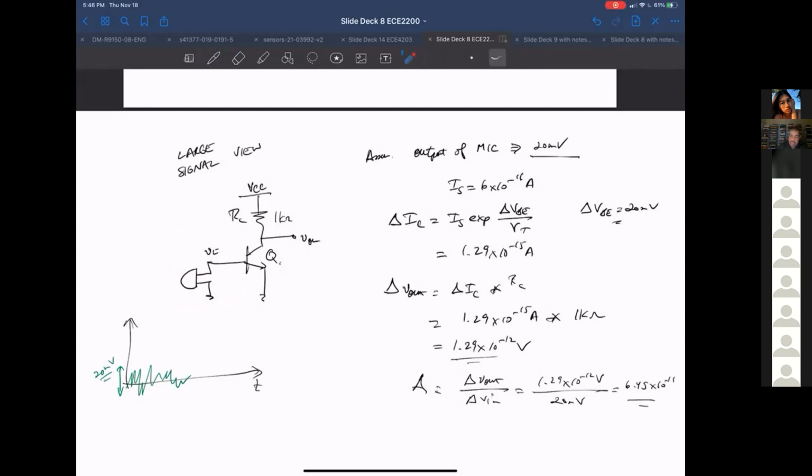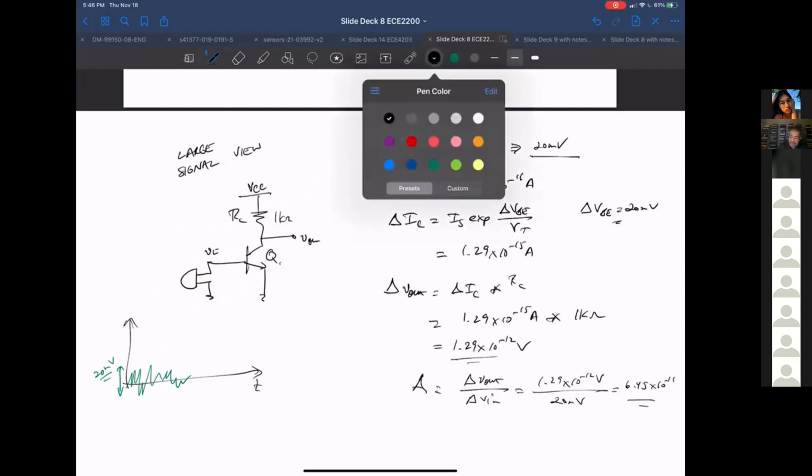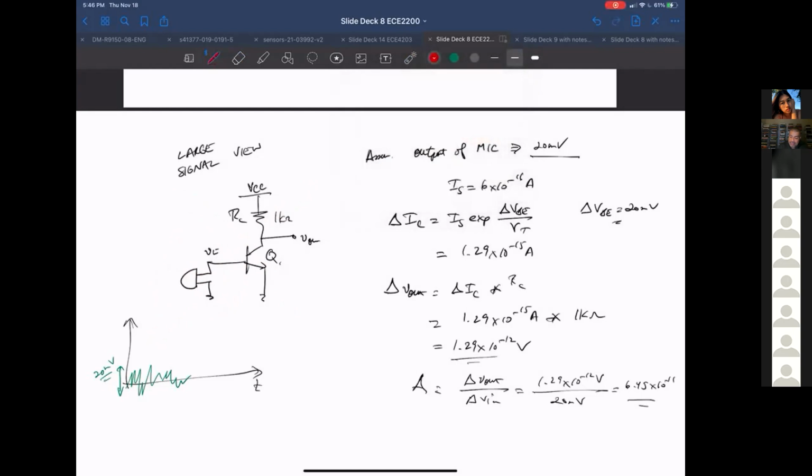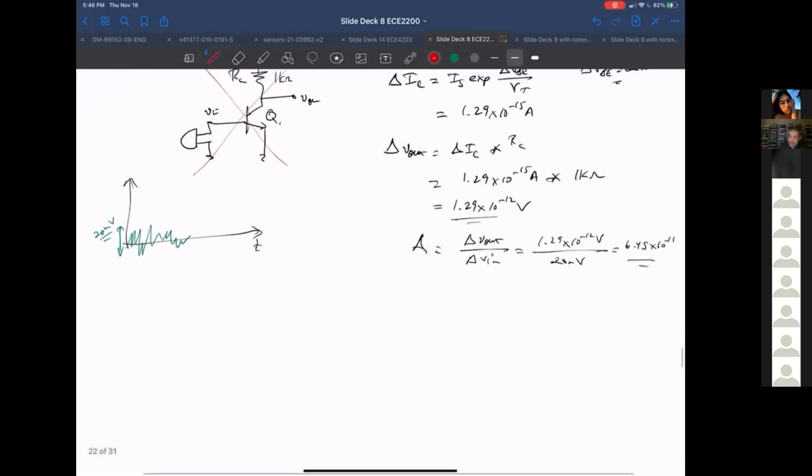Okay, so this thing is, I'm going to guess at least some of you, even after this class, are going to do something like this at some point. I've done it, just not thinking it through, right? Just hook it up straight. You're not going to get anything coming out because you don't have a bias. You haven't created a bias at the input.